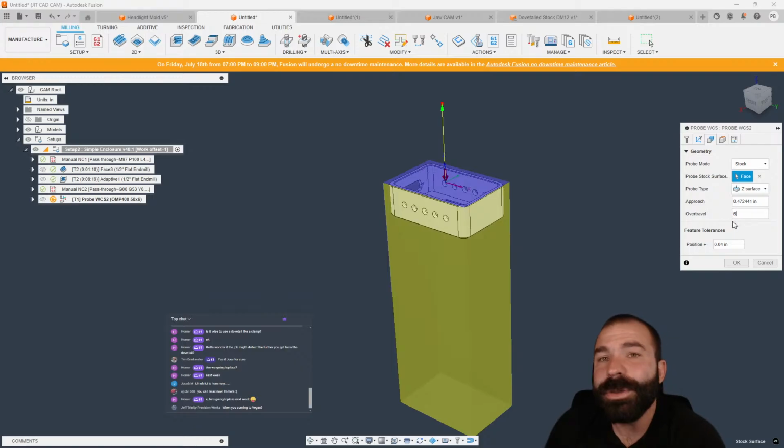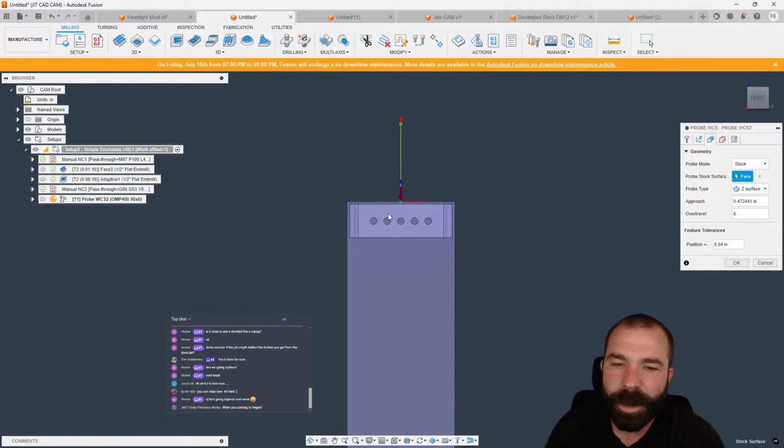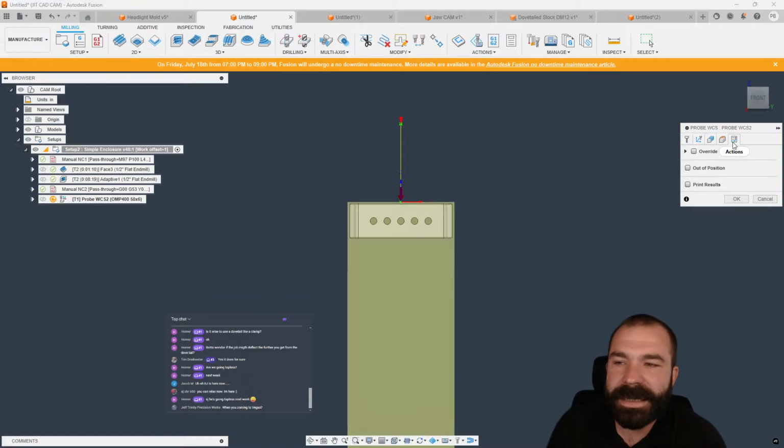But the issue is going to be what happens when we put a new piece of material in, right? When you get that new piece of material in to be machined, I would have to manually go in and probe the very first one again, right? Because my work offset right now is dropping each time. So that first time in to probe, if you guys haven't seen this or done this, don't do it, but you would wrap it down and break the stylus, right? This is where we can command a probe to be overridden.